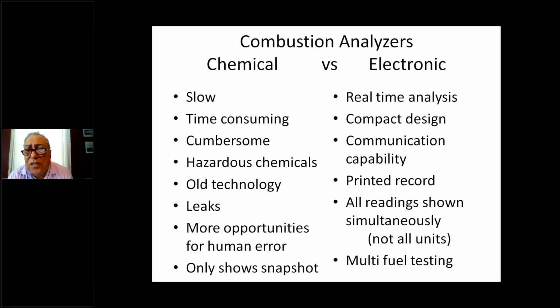You can get your combustion efficiency to where you want to be with just about any fuel, but again, the chemistry of the fuel is a little different. I think that answers that question. The chemistry of the fuel is different between kerosene and standard fuel oil, or even biofuel. It's all different. Your analyzer will take all that into consideration when you select the particular fuel you're testing.